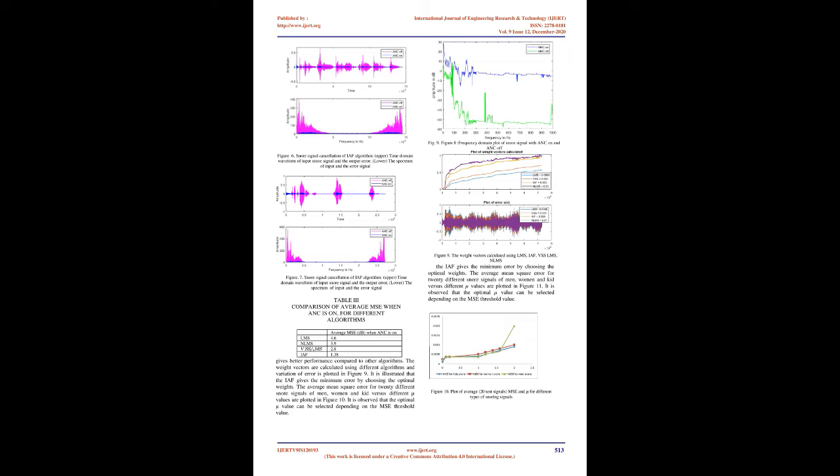Problem formulation. Figure 4: System model of IAF used for masking snore signal. The system model of the multi-channel, J-K-M, adaptive filter is as shown in Figure 4. J denotes reference microphones, K denotes secondary sources and M denotes error microphones for picking error signals.